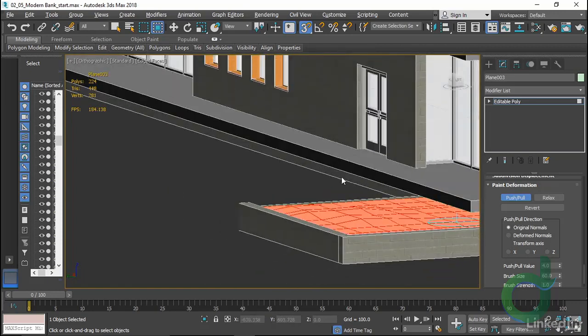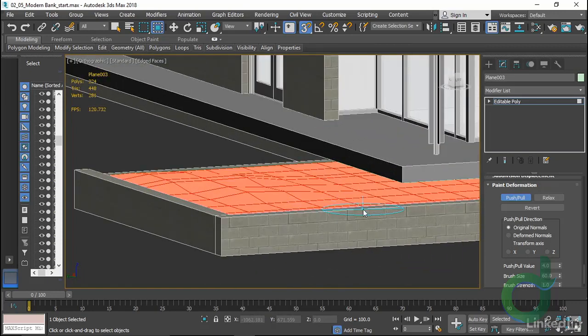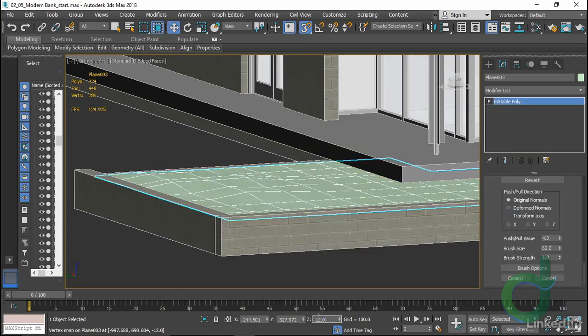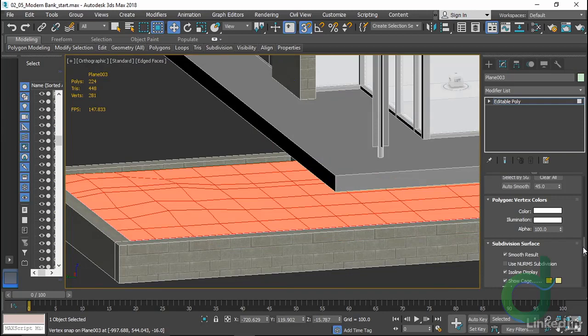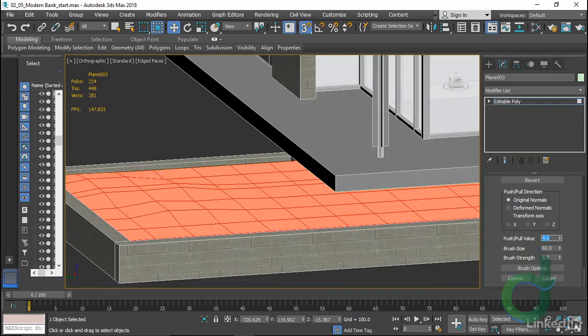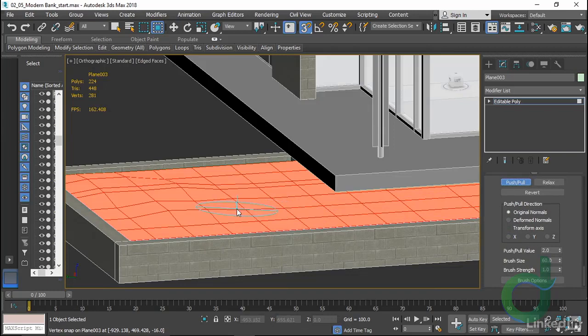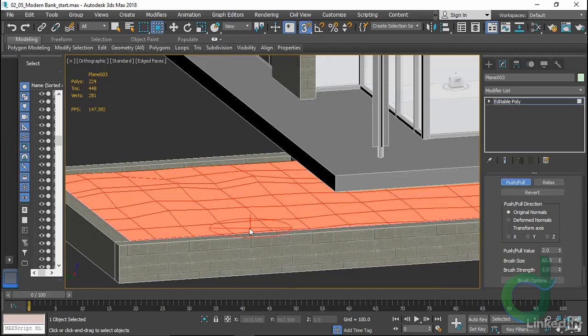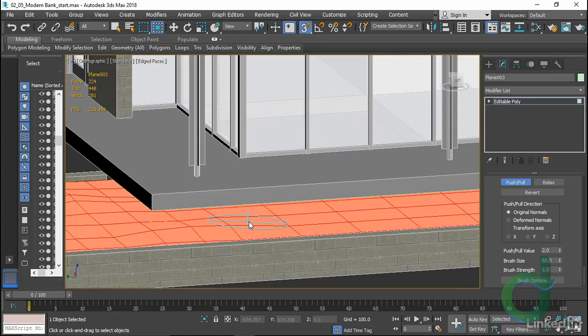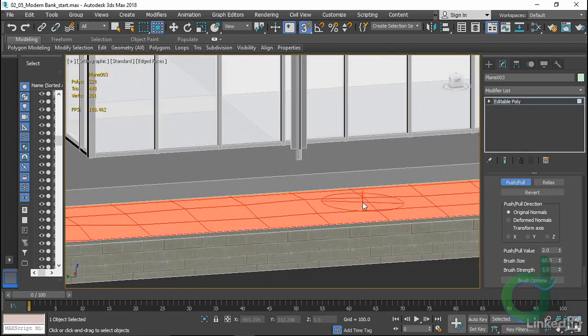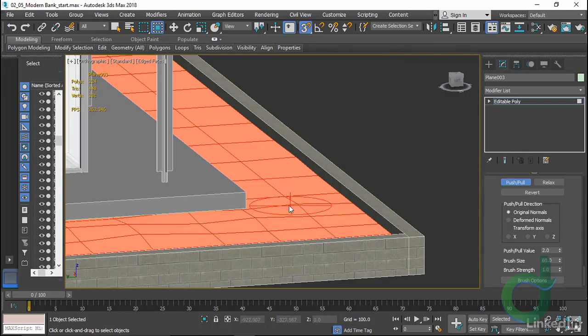Alternately, if you're finding it's rising up too much, you can always push it down further and then brush it up. I'll take my overall terrain and push it down to a -16, and then start to brush it up higher. Here's my push-pull at 2, and just going to brush in a little variation. All this is doing is affording me the opportunity to have ever so slightly different terrain. A little up, a little down, a little bit here and there that's just, well, slightly different from everything else.